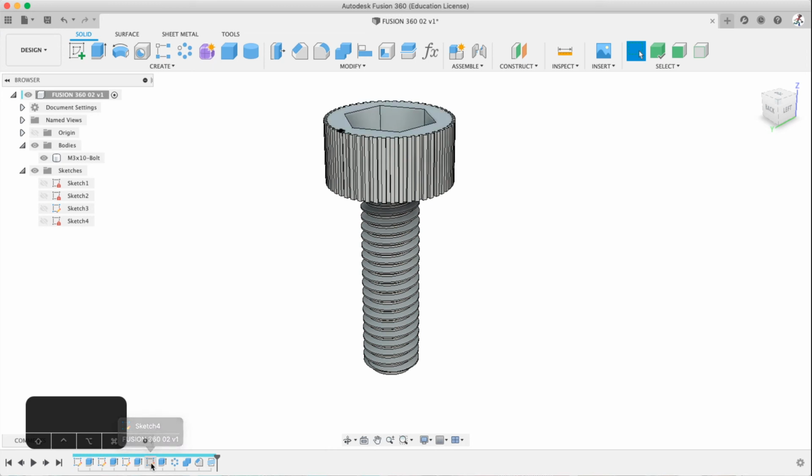And here is an actually really important thing. I hope you're still watching. If you are, really important. If you remove, let's say I make a box back here, or let's say I remove this sketch, anything after it that uses that sketch as a reference. So the first one is the main head sketch. If I remove that sketch, basically everything else here becomes a little messed up. If it becomes yellow, it's still workable. Fusion can still work it.